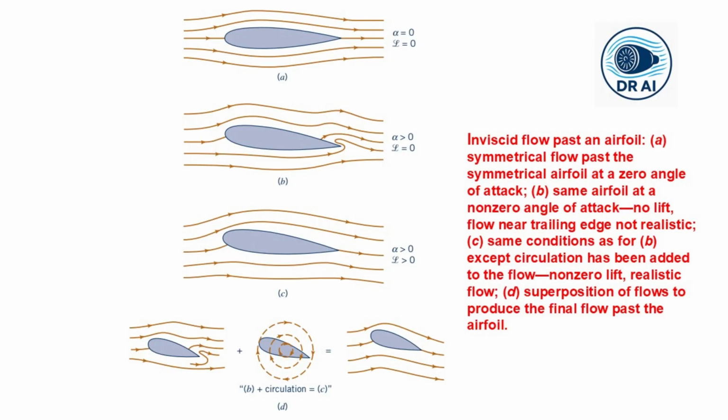The flow goes around the trailing edge from the lower surface to the upper surface with an extremely high velocity and a stagnation point somewhere on the upper surface. So this does not match what we observe experimentally. More importantly, the potential flow predicts zero lift for this configuration, which we know is wrong. Real airfoils at positive angle of attack definitely produce lift.